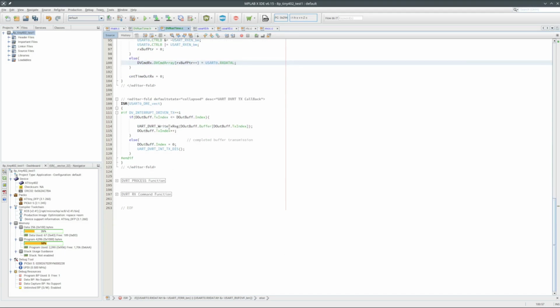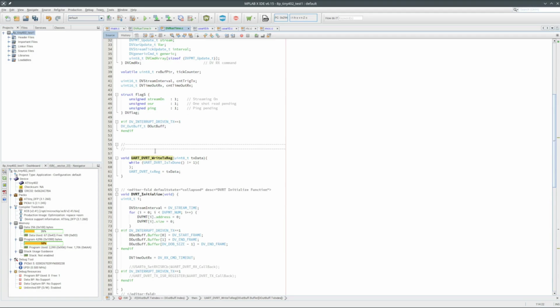Now for the data register empty interrupt, it calls a write register function. I'll do away with that in the future, but for now I'll just put in the transmit register value. And this will only be called when it's ready for data, so I'll comment out the data ready check.